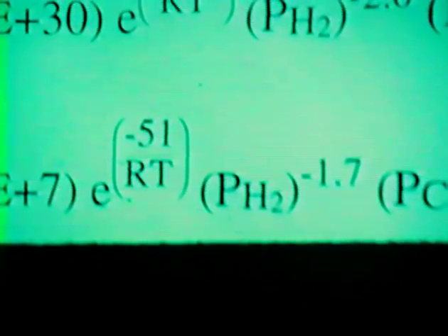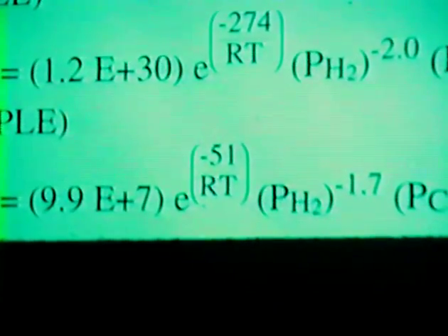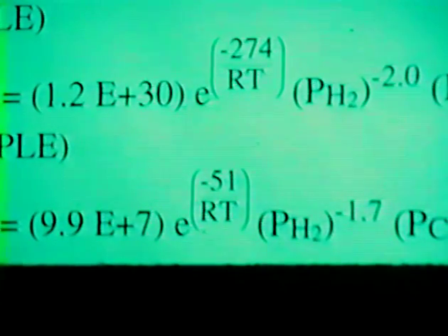Looking at the generalized power law expression with A infinity values ranging from 0.1 to nearly 0.6 for different conditions, and this includes the analysis of all of those. We see not much change in the hydrogen CO effects, but we do see that the order of deactivation is reduced to nearly 1. And we see that the activation energy reduces from 274 kilojoules per mole to 51. And this is in very good agreement with experimentally determined values of 30 to 40 kilojoules per mole on nickel and ruthenium aluminum catalysts.